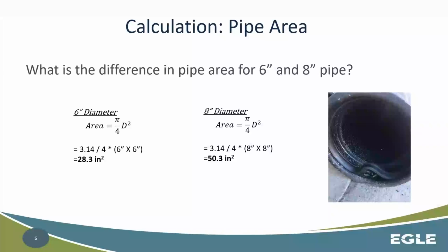So, as I was alluding to on that previous slide, you have this opportunity, especially if something is inadequately sized, if water mains are oversized or undersized for a given system, for stagnation and potential aesthetic, as well as maybe even health concerns, depending on the situation, right? If too much water is sitting there for too long. So this is just getting you into that calculation mindset that, hey, there's a big difference here between even something as simple as a 6-inch pipe to an 8-inch pipe.